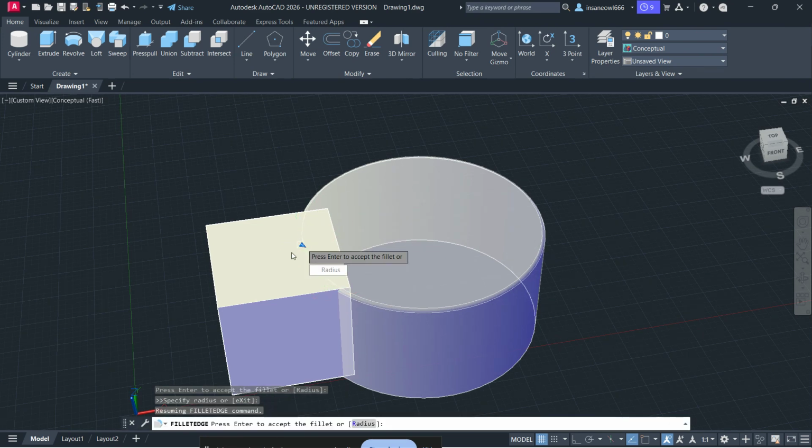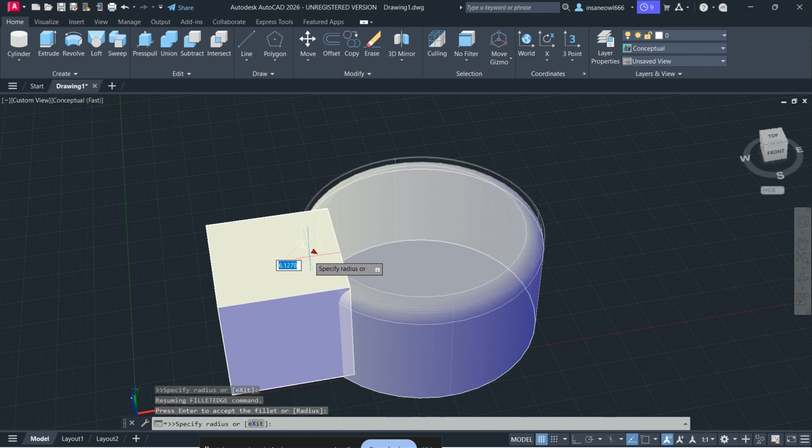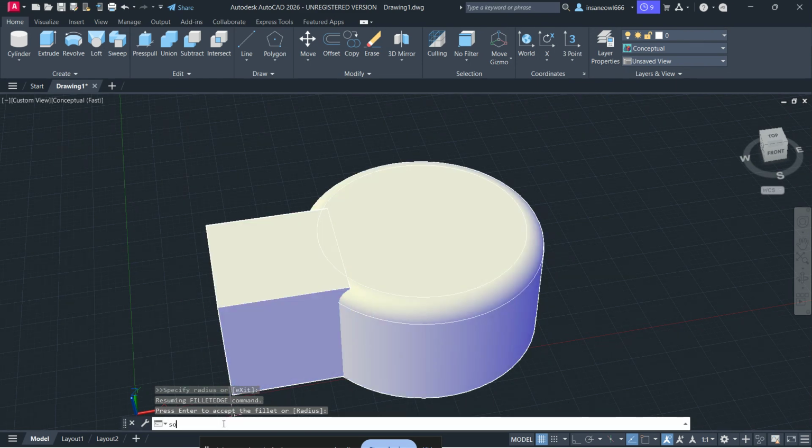Next, clean the body. In AutoCAD, run SOLIDEDIT, then choose Body, then choose Clean. This command helps strip out redundant vertices and edges that can create noise in the geometry. It's a very useful step when you suspect the object has become messy after multiple edits, unions, or subtract operations. After cleaning, try the same command again and see whether the error is gone.